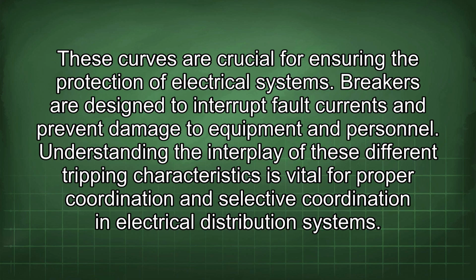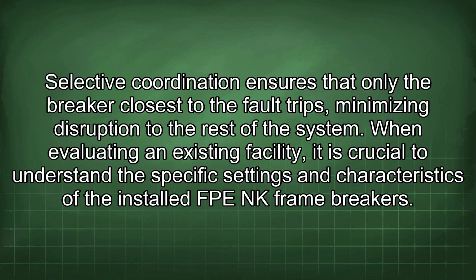Understanding the interplay of these different tripping characteristics is vital for proper coordination and selective coordination in electrical distribution systems. Selective coordination ensures that only the breaker closest to the fault trips, minimizing disruption to the rest of the system.